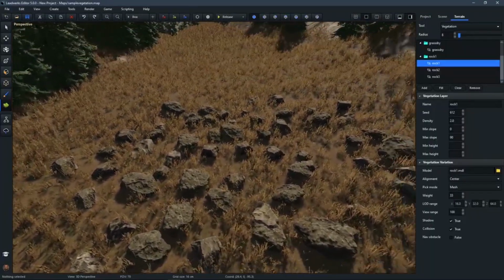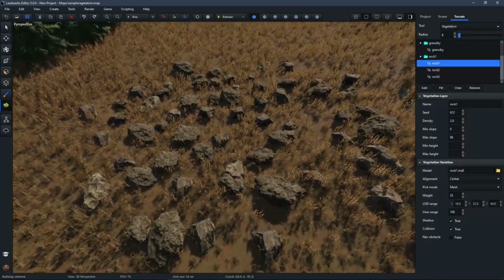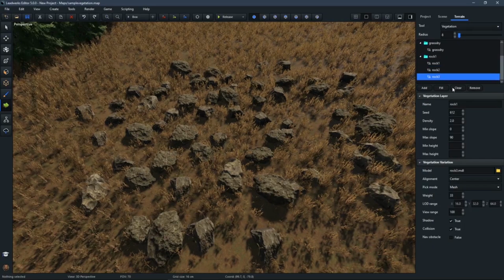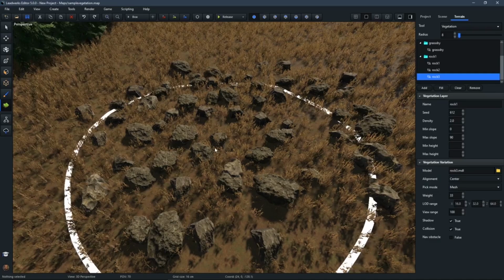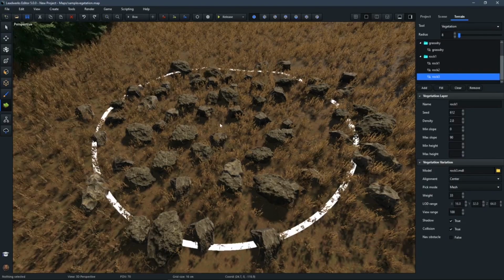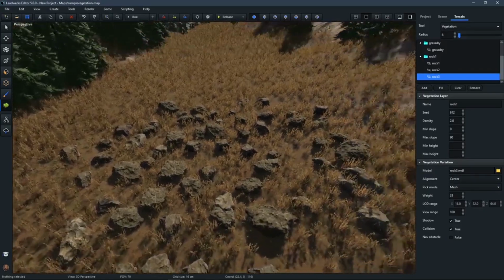And that's really nice because you can just paint a bunch of them down and they'll automatically be randomly chosen. For each variation, the variation properties are down here, and you can even see this weight value. You can change this to make a certain variation appear more or less frequently. So if you have a certain tree that's very distinctive looking and you don't want it showing up a whole lot, just every once in a while, you can decrease its weight there, and it will be less likely to be used.